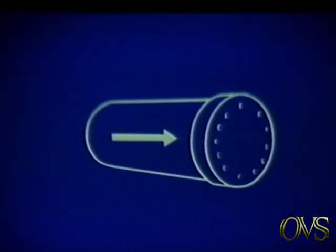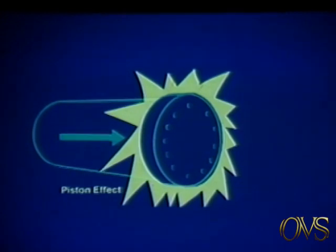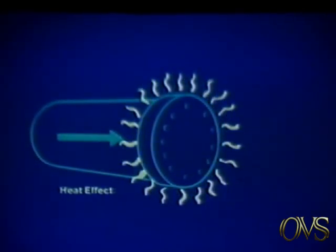The first effect is like the combustion sequence in a diesel engine. A very quick pressure rise against a closed valve or other internal block has an effect like a piston in a diesel engine cylinder, possibly causing an explosion by pressure shock. In addition, compressing a gas very quickly will build up heat within the system. Simple inert nitrogen, quickly compressed from 0 psig to 1300 psig, could reach 1500 degrees Fahrenheit, well above the auto-ignition temperatures of the NGL mix.